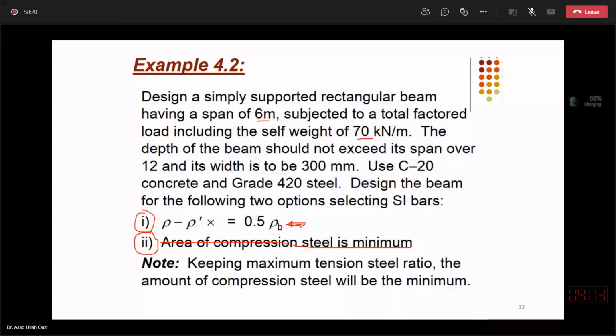You obviously will ask the architect about the floor finish thicknesses, type of floor finish, and type of building, so as to select appropriate live loads and structural use. But finally, the drawings and other information with cross sections will be provided to you with some architectural restrictions. And then finally, you will get to such spans and loads.